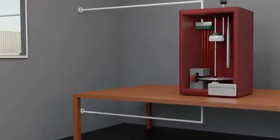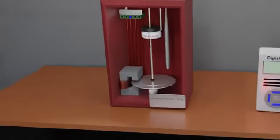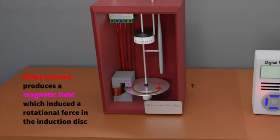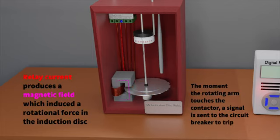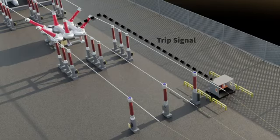Inside the relay, let's take a look at what happens when we have a 200 amp line current and a 10 amp relay secondary current. The current through the relay has generated a magnetic field which induces a torque in an induction disc. The induction disc therefore rotates, and if it rotates far enough, a rotating arm hits a contact, and this initiates the instruction to the circuit breaker.